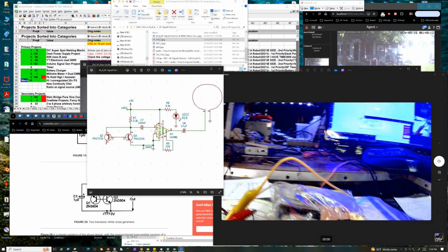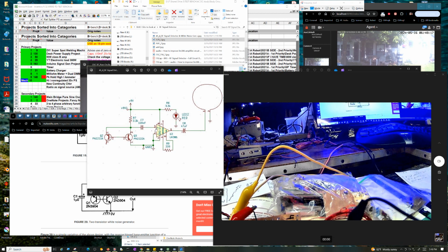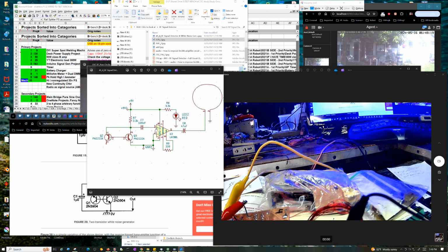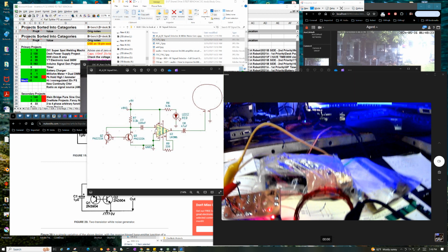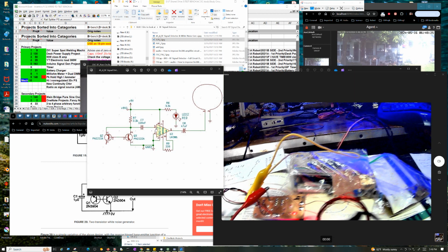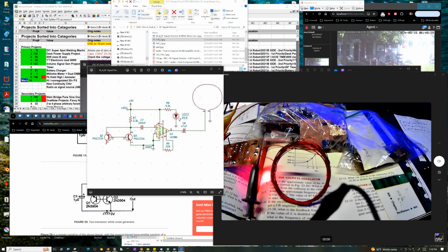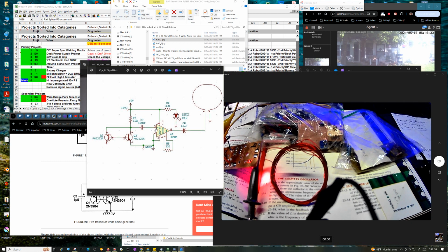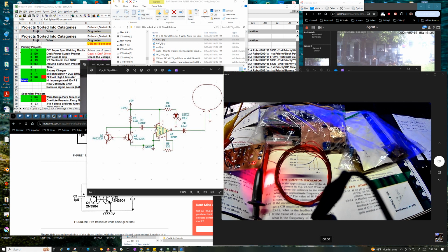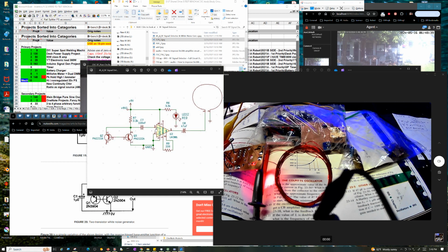I'm probably messing up the 386 doing that, come to think of it, because you really shouldn't inject a signal that way unless it has a DC offset built in. But at any rate, just for testing purposes, it's very interesting. But like I said, if you had a more powerful amplifier, you could just keep it an air inductor and just wind more turns, but make it tighter winding or something, so you can inject signals into a definite area of your circuit.